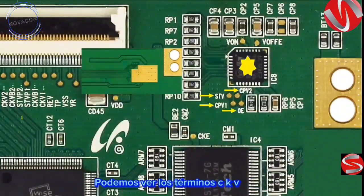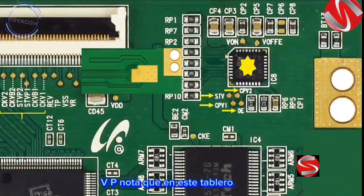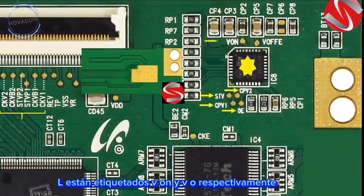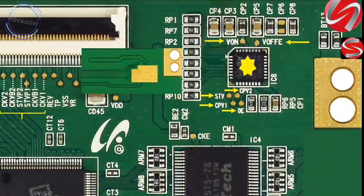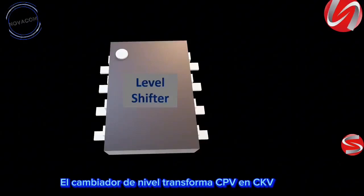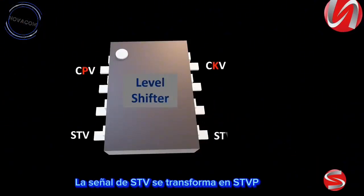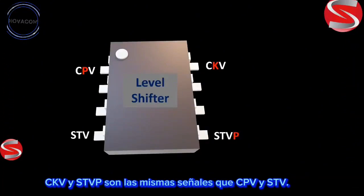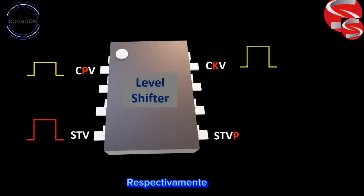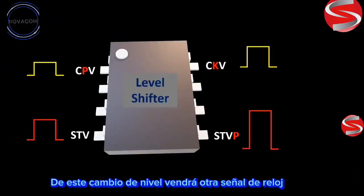We can see the term CKV, but there are also other terms such as CKVB and STVP. Note that on this board the VGH and VGL are labeled V on and V off respectively. The level shifter transforms CPV into CKV. The STV signal is transformed into STVP. CKV and STVP are the same signals as CPV and STV respectively, but CKV and STVP have a higher voltage value.